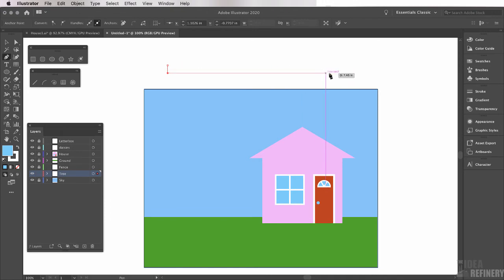I'm now going to move across my artboard. I'm just going to click there to create an anchor point, and I'm going to finish this shape by coming back with my pen tool, clicking on the original anchor point. I now have a very long triangle lying on its side. Why is it on its side? Well, I find that custom art brushes made in Illustrator work a little bit better when they are created horizontally. Now, the issue I have with this graphic right now is that it's got the appearance of the last object I had selected, the white stroke and blue fill of the window.